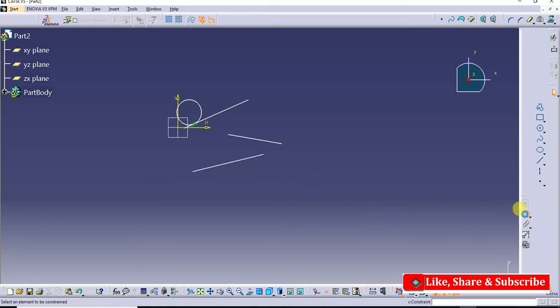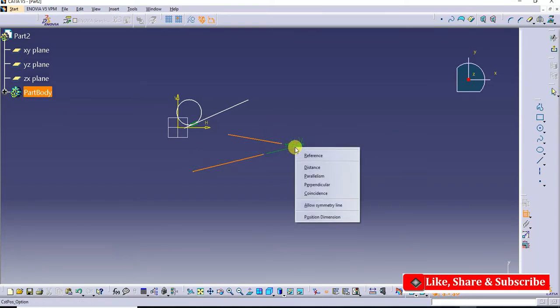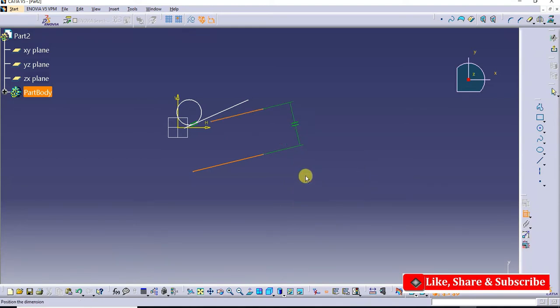Now I want this line to be parallel to this. I'll select this and this, then right click the mouse button and click over parallelism. So both the lines become parallel to each other now. This symbol indicates that both the lines are parallel.